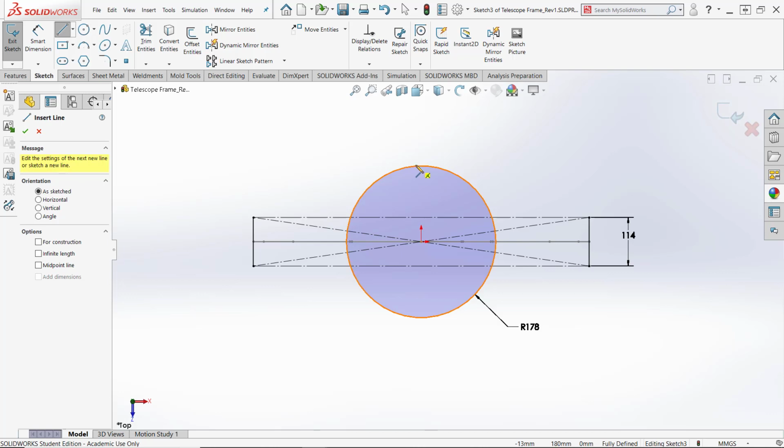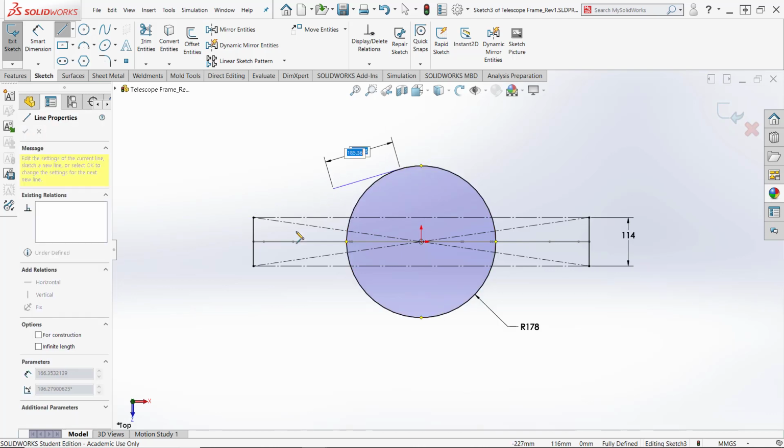When you go to draw this line, don't click on the quadrant, but click someplace on the circle and hold the mouse button down. Don't let go of the mouse button. And see, it's going to automatically put that tangent on there. And so I'll come over to here, and I'll do the same thing. And actually this time I didn't hit it in the right place, but hopefully it'll put it on there for me. And I'll do another line, and I'll do that up here.